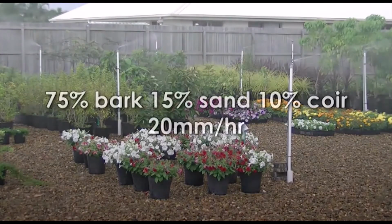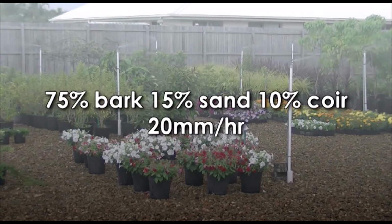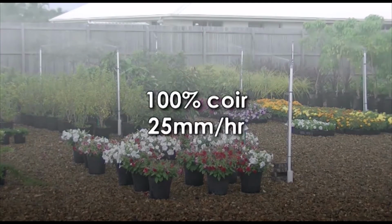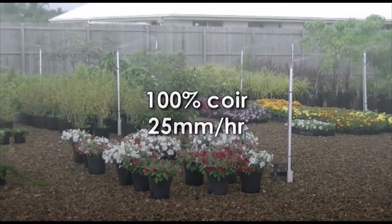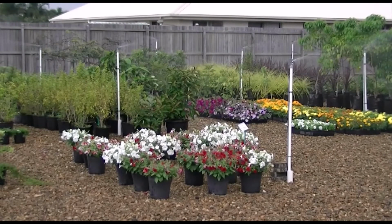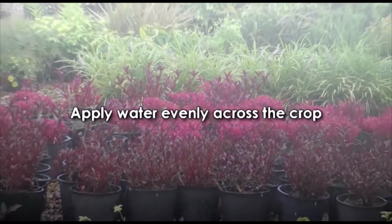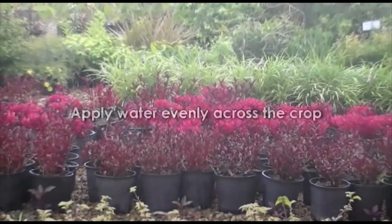A growing media consisting of 75% bark, 15% sand, and 10% coir would have an absorption rate of approximately 20 mm per hour. A growing media consisting of 100% coir would have an absorption rate of approximately 25 mm per hour.